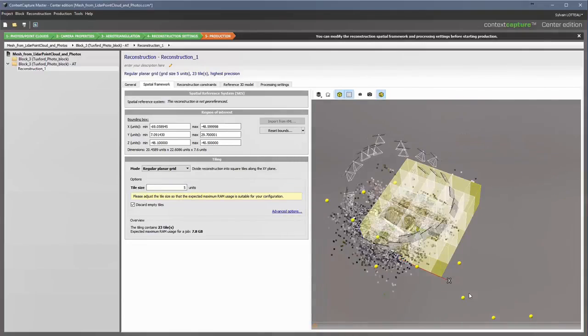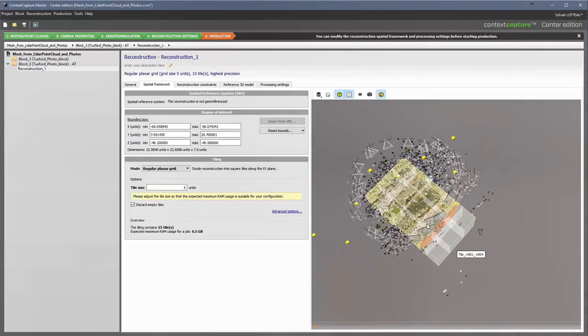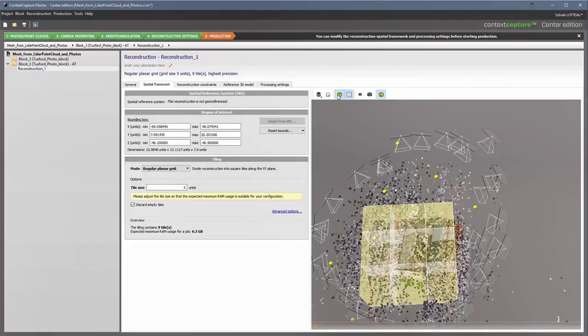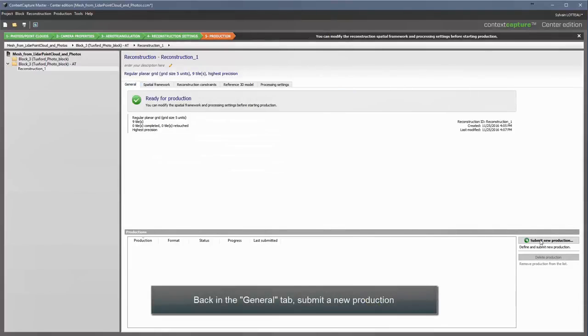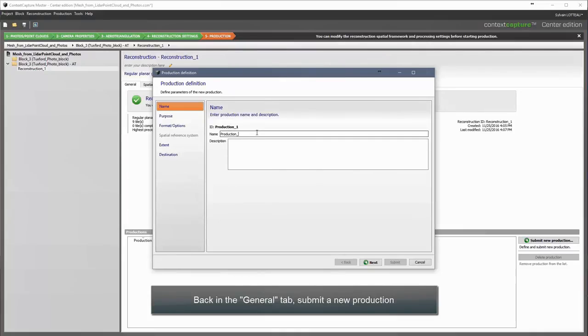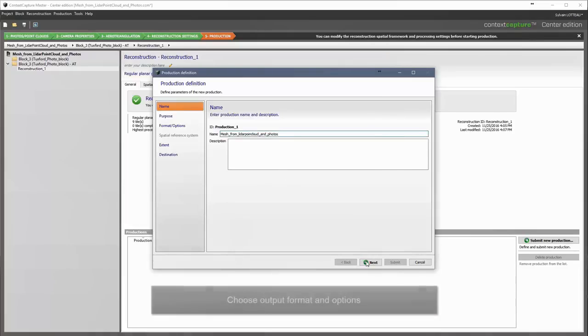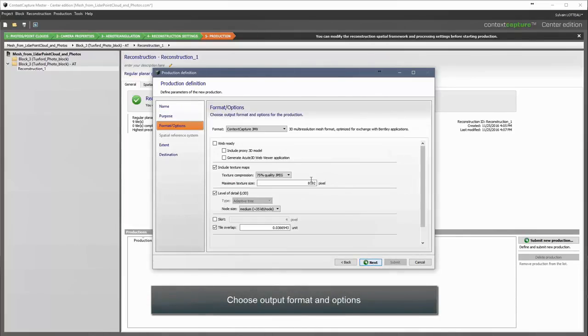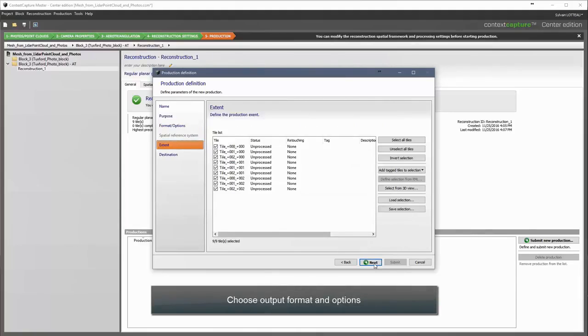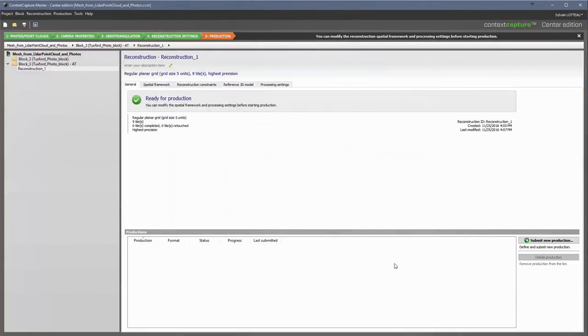One thing that I want to point out here is you see that we're changing the area of concern that we're reconstructing. It will save you a lot of time. When you're taking photographs, you're getting a lot of things in the distance, which are very helpful for your parallax to calculate where the camera position is. But when you're doing your reconstruction, creating your mesh, I don't believe you need everything outside of there. That is stuff in the distance. So I recommend changing your spatial constraint to tie it into just the area that you're working with. It creates a nice small mesh for you, very easy to work with.